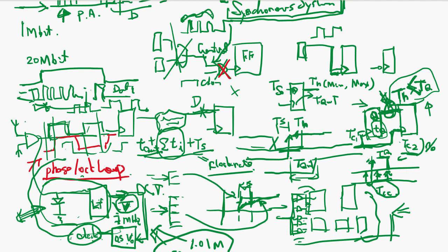It means you can delay your oscillator's clock by a certain amount, the stepping, and that stepping delay clock is often used in IC chip testers. Those Teradyne testers use a lot of those circuits.